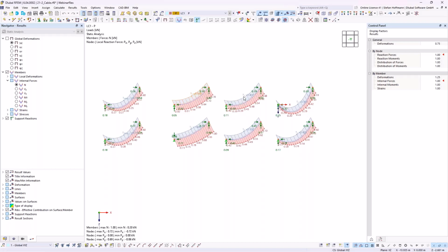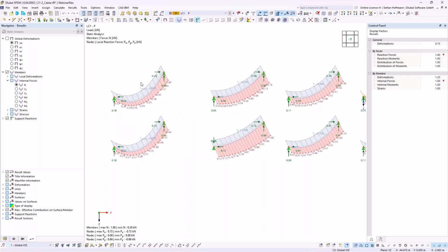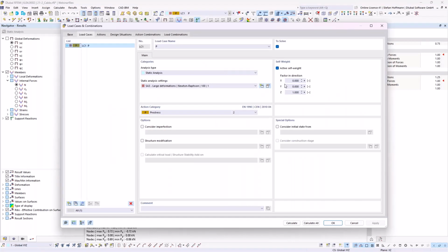We can have it less. This is also stable. This is also stable. And if I would lower it even more, then my structure will become numerically unstable or nonsense inner forces will arrive. And this is what this function is doing internally. So it's a minimum force definition to reach a certain convergence or equilibrium. So of course, the dead load is activated for both models.